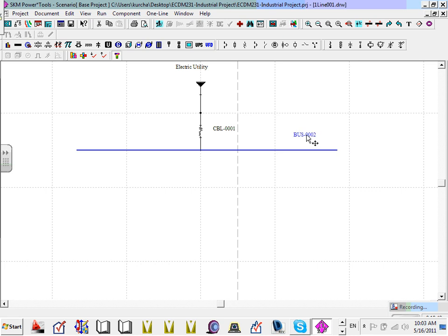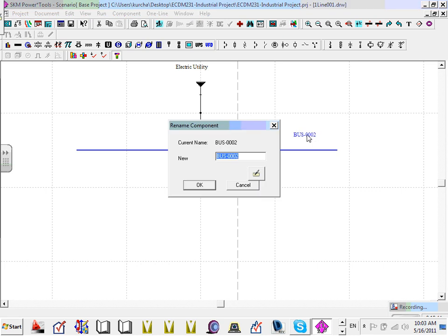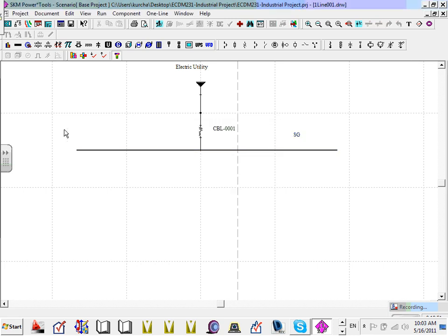Brad, can you see that bus here? The name bus here, bus tool. Can you guys click on it and call it switchgear, SG? How does it grab it? If you hover over it, you'll get a line that looks like a two-way arrow. Can you guys see that? Hover over it at the end and just hold the left. Mine doesn't expand, it moves. If you look at the cross here, this will move it.